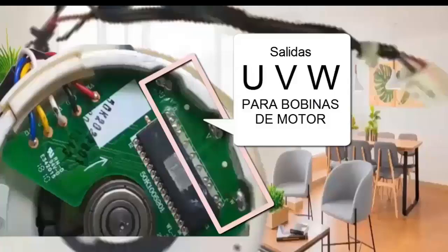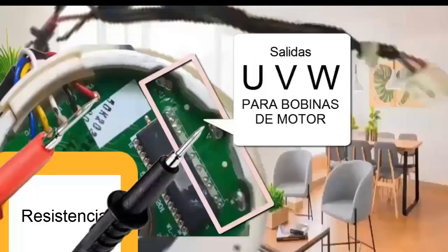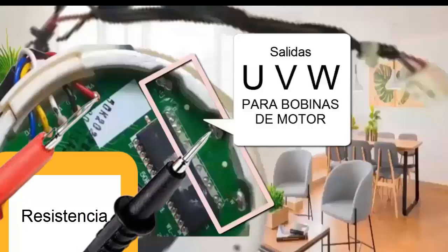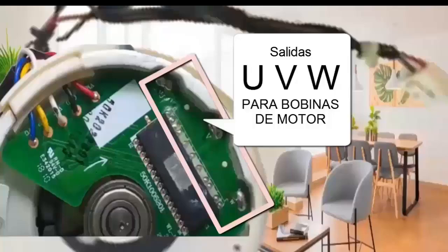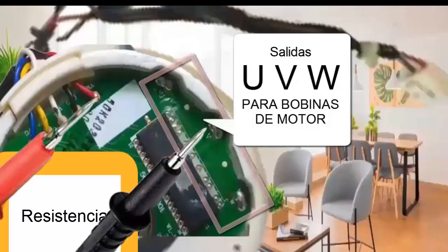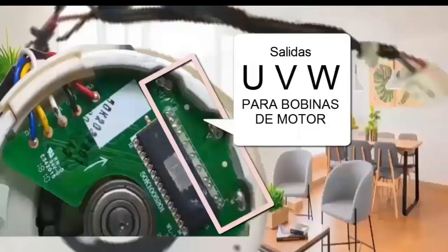6. Verifying issues on the electronic board. Measure electrical resistance using the multimeter from the high voltage supply, red wire, to each of the outputs to the motor coils. All readings should be identical. This procedure should be carried out by placing the red probe on the fan's red wire, and the black probe on each of the internal fan board outputs, then repeat with the probes reversed. If any measurement differs, the control board might have an issue.